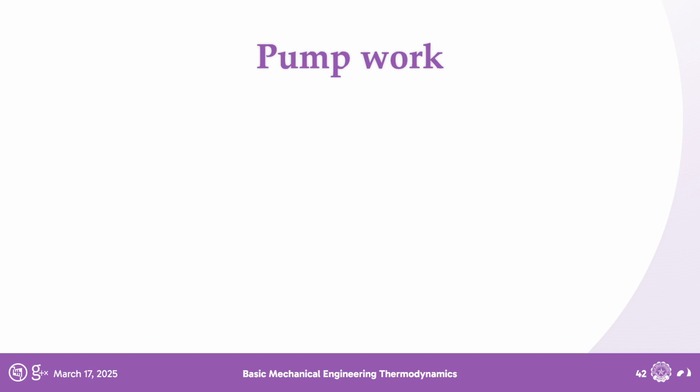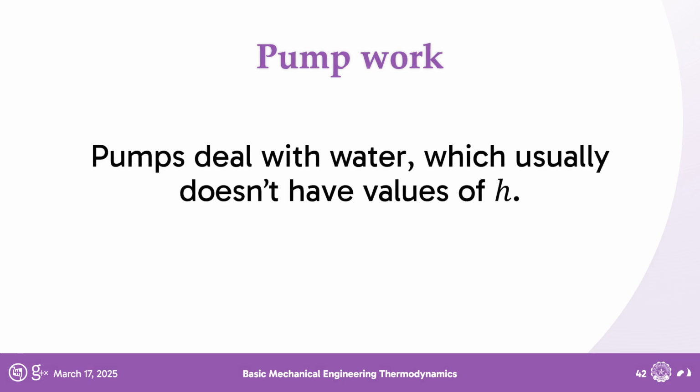And now, we have a special case of work computation for a pump. Like I said earlier, a pump handles liquids, and usually pumps deal with water. And there's a big problem with water, especially liquid water, aka compressed liquid water. We had this problem earlier where we don't have values for compressed liquid, so what we do is an approximation.